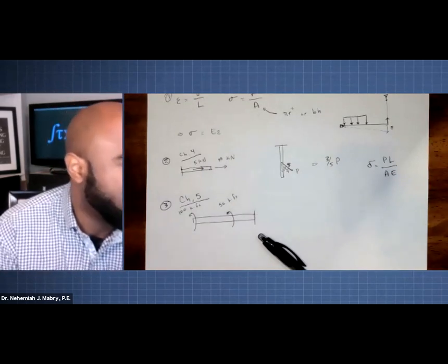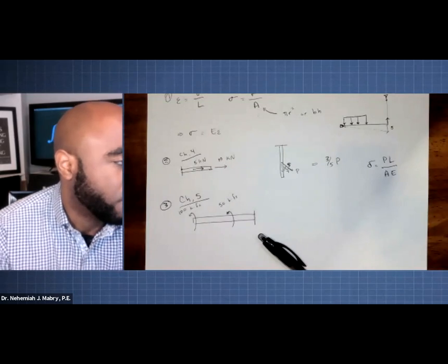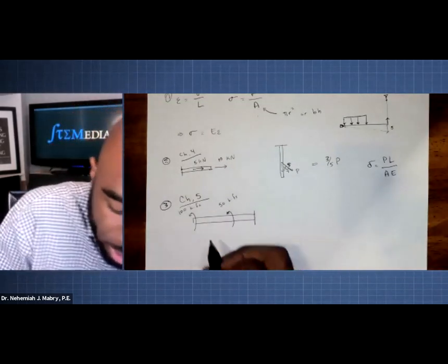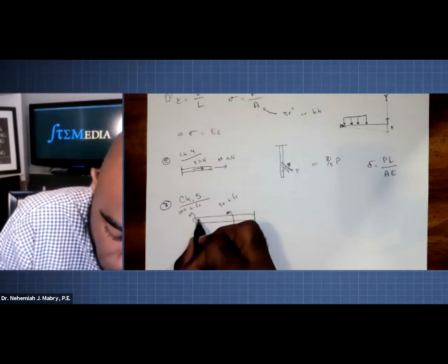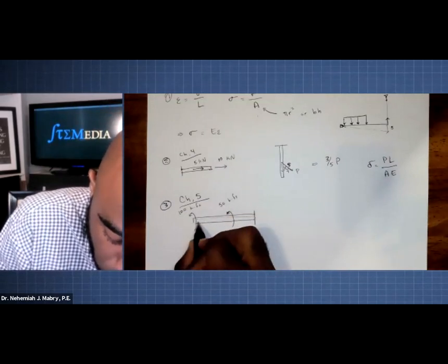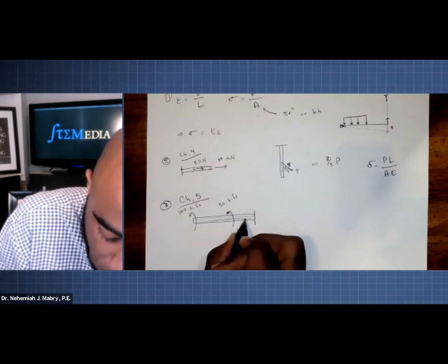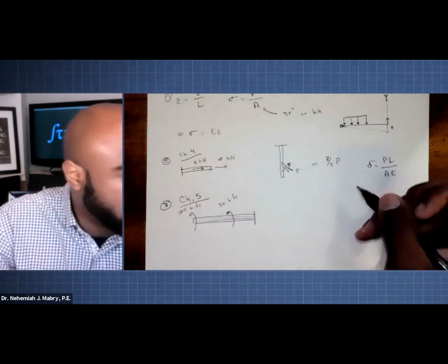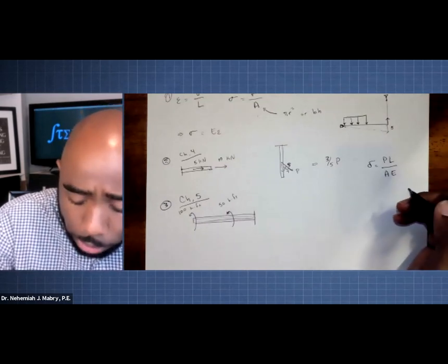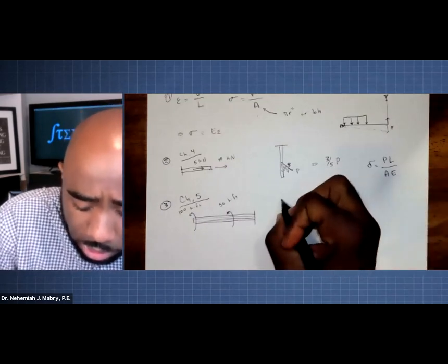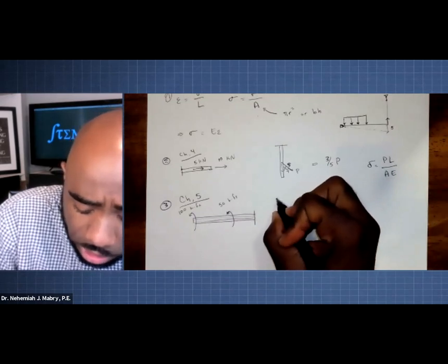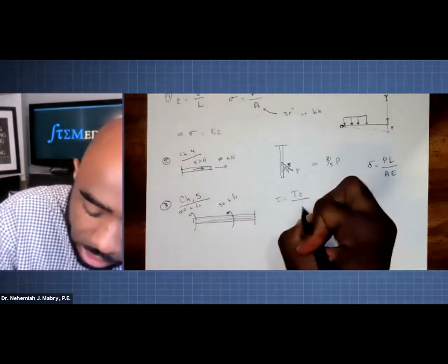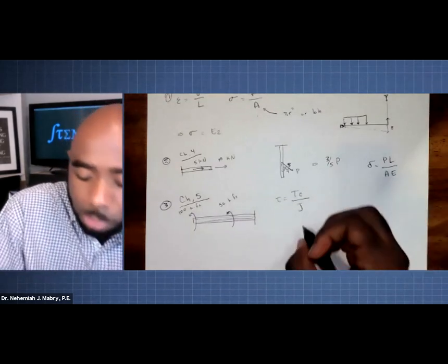And then you may be asked to solve for any measure of things. It could tell you that this is also a hollow tube, which is going to change the way that it's being applied. And what you should be able to solve and interchange is equations such as shear stress, if y'all remember this one, tau equals TC over J. Remember, J is the polar moment of inertia.